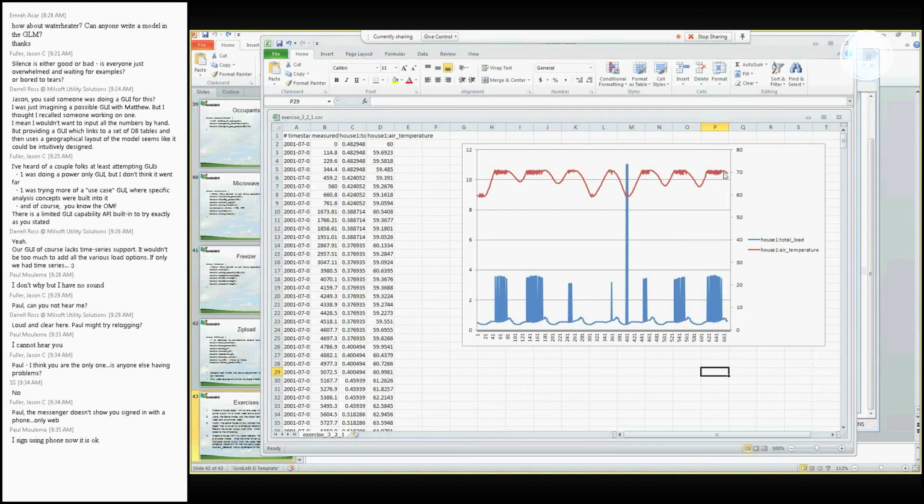So you can see here, of course, remember we were trying to maintain the air temperature at 70 degrees. At night it was drifting down, and then as the outside air temperature came up, our inside air temperature came up, and we can start seeing that it's trying to maintain it around 70 degrees. So you can see it kind of cycling on and off, and then down here in the power output, you can actually see the duty cycles starting to cycle on and off.